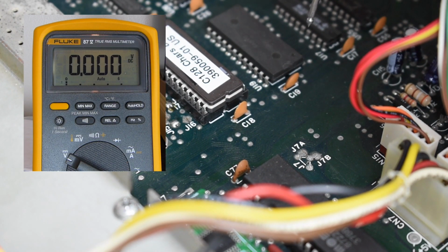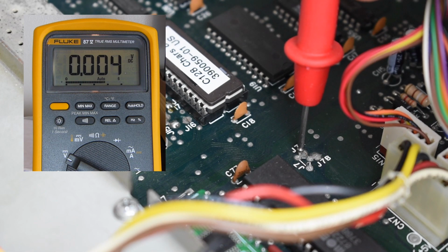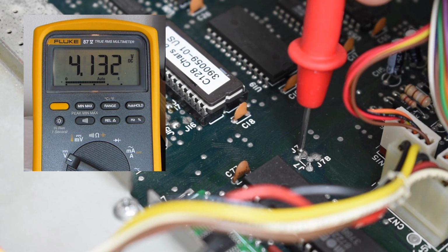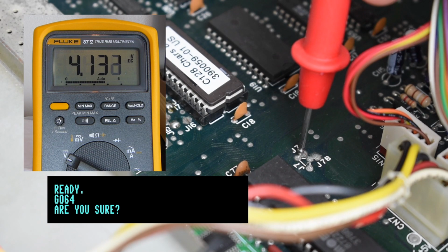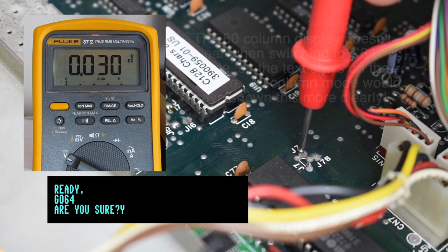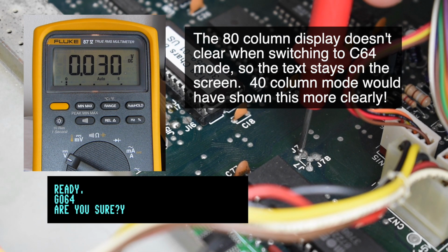Okay, let's look at jumper 7A. So if I put the probe on 7A, you can see it's reading 4 point something volts, near enough 5, but we're in Commodore 128 mode. So if I type GO 64 and jump into Commodore 64 mode, then you can see the voltage drops down to near 0 volts. So that seems to work the same way as the circuit diagram too.